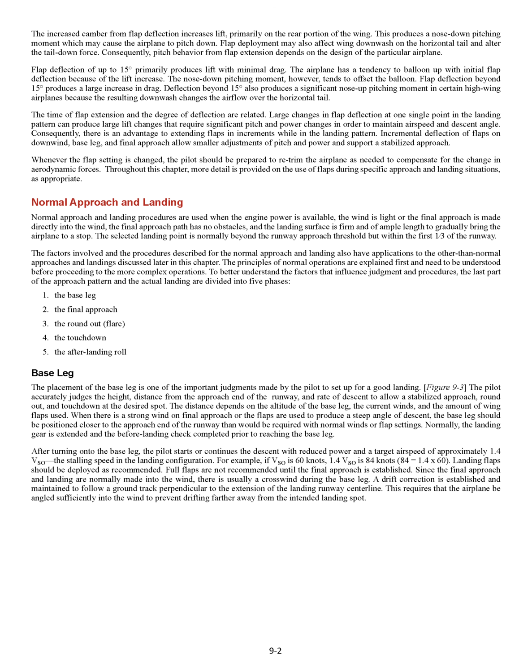When there is a strong wind on final approach or the flaps are used to produce a steep angle of descent, the base leg should be positioned closer to the approach end of the runway than would be required with normal winds or flap settings. Normally, the landing gear is extended and the before landing check completed prior to reaching the base leg.